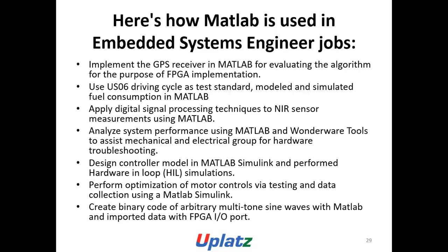Design controller models in Matlab, simulate, and perform hardware-in-the-loop simulations. Perform optimization of motor controls via testing and data collection using Matlab Simulink. Create binary code of arbitrary multi-tone sine waves with Matlab and import data with FPGA IO port.